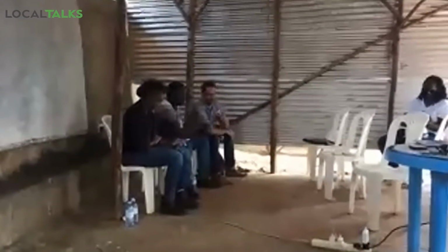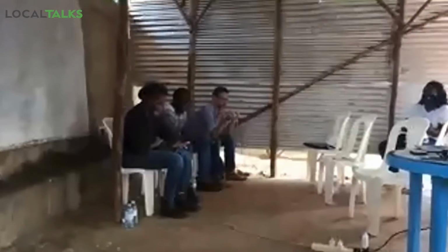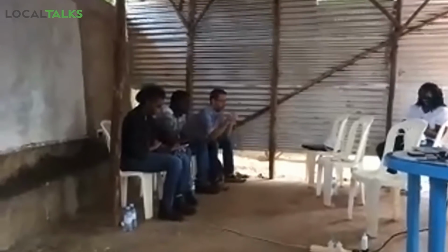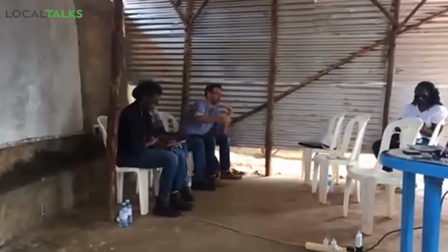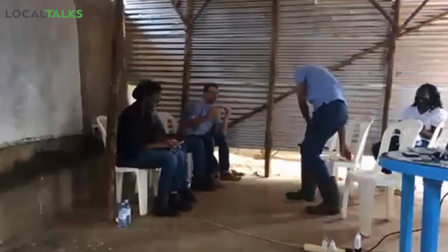So just to add on to this, you may recall the photos and the drawing that showed the barbed wire, the 2 strands of barbed wire that are in each course. At a certain spacing, we have added binding wire to those strands of barbed wire that we made stick out on either side of the wall. And with those binding wires, you then fix chicken mesh, very ordinary galvanized chicken mesh. You fix that, and that is what then provides the basis for the plaster.